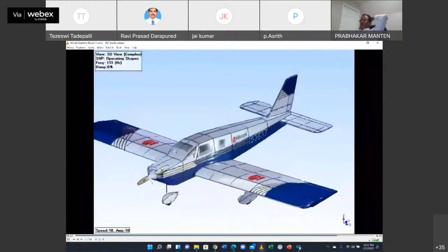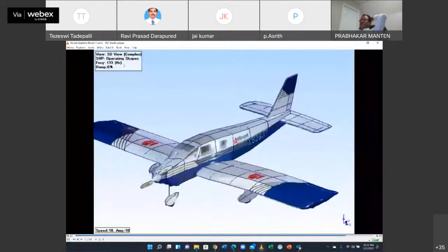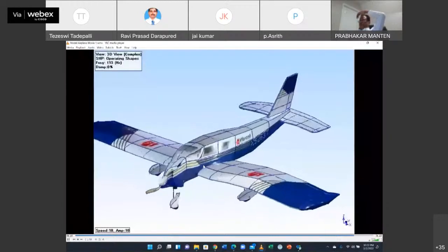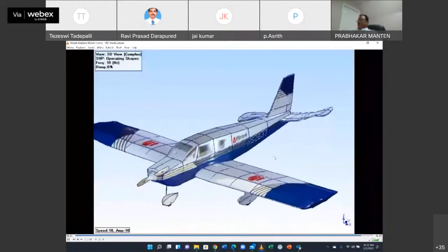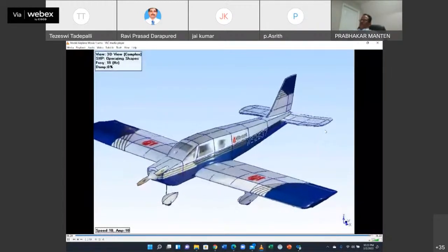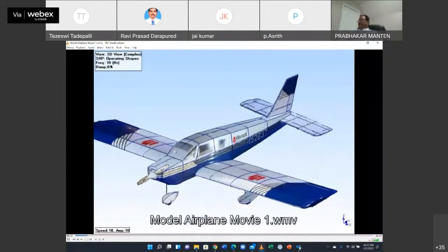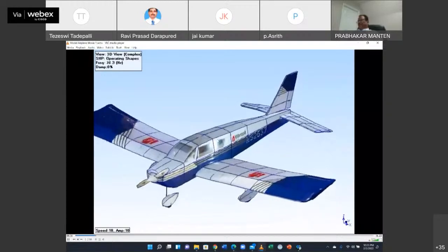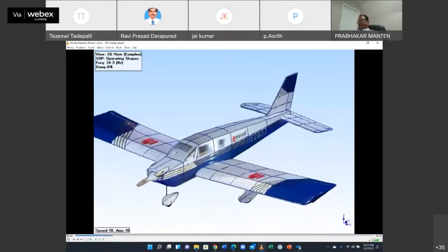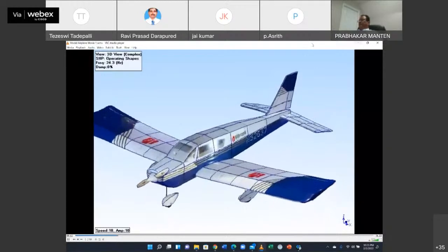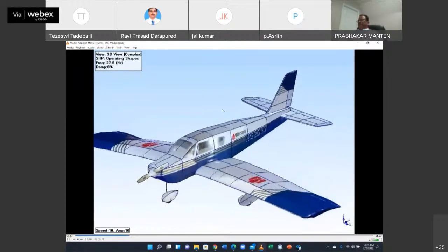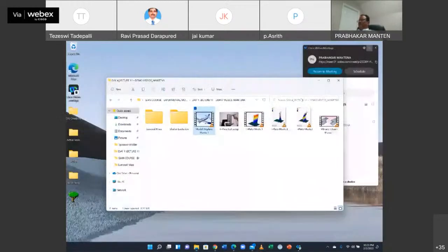Now you see the out of plane movement of the center at this hertz. There's a frequency over there, movement over there, and back and forth. So folks, that's the fun part of doing this whole thing carefully. It takes a lot of work, carefully acquiring the data from the triaxial accelerometer, and tapping. It's a model airplane that was built for demonstrating and letting students know how much fun this modal analysis is. What else do I have to show you?